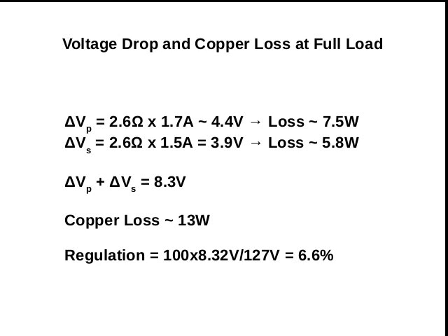Now for some applications, some more windings are added to the secondary to compensate for the voltage drop caused by the wire resistance at full load. In our case, doing so would make the secondary have an open circuit voltage that could exceed the mains nominal voltage. I decided to leave the secondary uncompensated, and if the voltage drop at full load occasionally becomes a problem, I can always use a variac to raise the voltage a little.